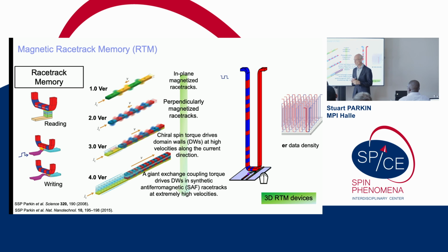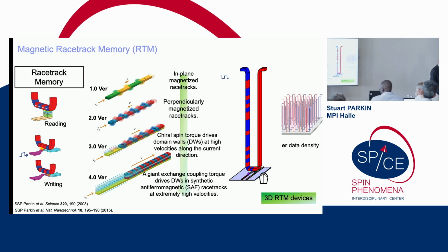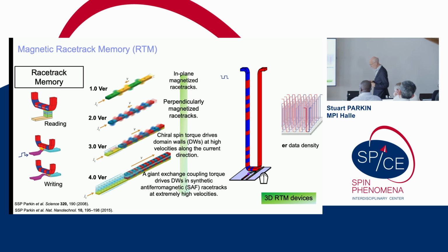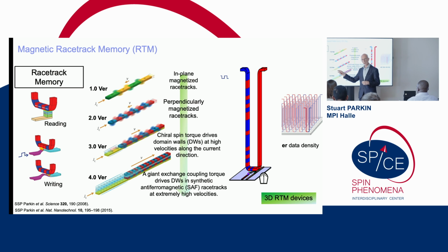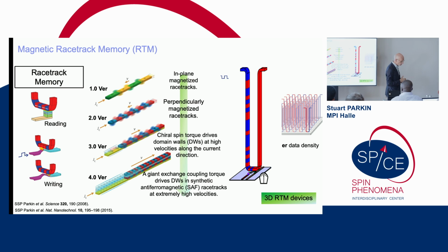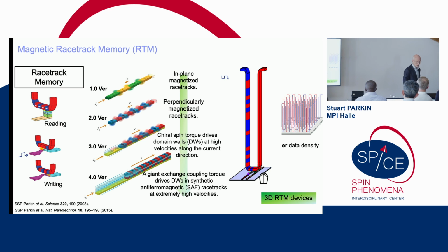And then eventually we switched to spin orbit torque, where we demonstrated that using the spin Hall effect we could transfer electrical current into transverse spin currents, and then the spin currents diffuse into the magnetic domain walls, providing torques that are more efficient than spin transfer torques by a factor of 3 or so, enabling the domain walls to move somewhat faster and actually in the opposite direction.